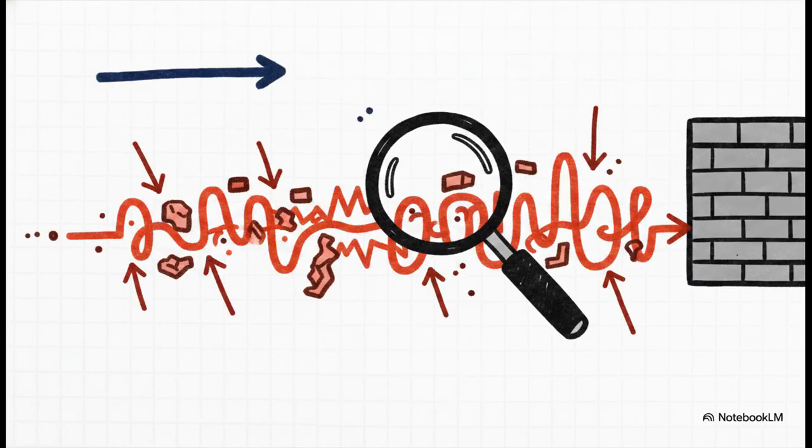So, the crucial point we really need to hammer home is this. When you are performing timing analysis on a real-time system, average execution time is just not enough. You must understand the worst-case execution time. Because execution times can vary wildly based on conditional logic or system delays, you must calculate the absolute maximum time a process will ever take to execute. In a hard real-time system, all of your scheduling and priority assumptions must be based on this worst-case scenario. That is how you guarantee, mathematically, that a critical deadline will never, ever be missed.